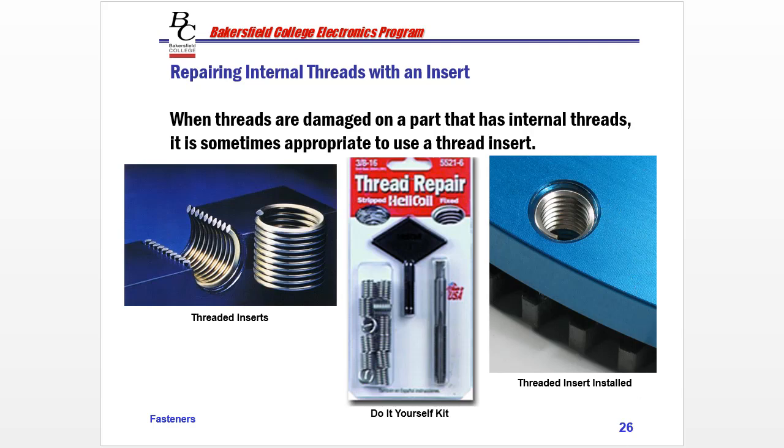They've been used a lot in the automotive industry, especially when maybe you put in a spark plug and you cross-threaded it. So instead of taking off the whole cylinder head and having it fixed or machined or replaced, they make helicoils that will thread in the thread insert, so then you can put a spark plug back in the hole. So these can be used in industry, around the house, anywhere you need to create a thread.